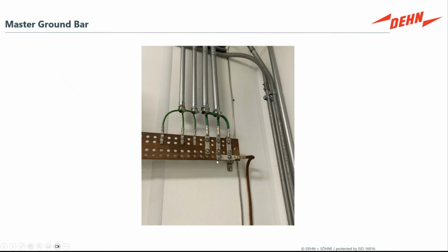You have a 2-hole lug, which prevents rotation and helps secure it indefinitely because it's not as subject to vibration conditions, with feeder conductors going to the associated ground bars and equipment throughout the structure. I like to point out that the metallic conductors are bonded at both ends, and that way you don't induce any kind of weird voltages in the metallic conductors that might otherwise flash over.